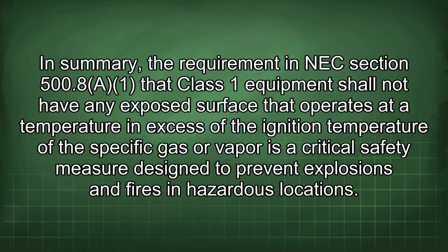In summary, the requirement in NEC Section 500.8(A) that Class 1 equipment shall not have any exposed surface that operates at a temperature in excess of the ignition temperature of the specific gas or vapor is a critical safety measure designed to prevent explosions and fires in hazardous locations.